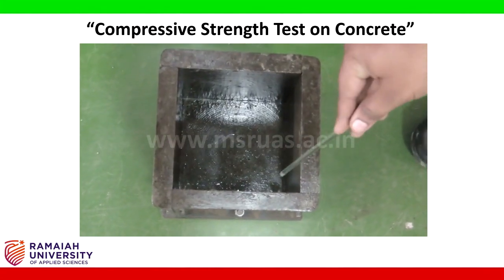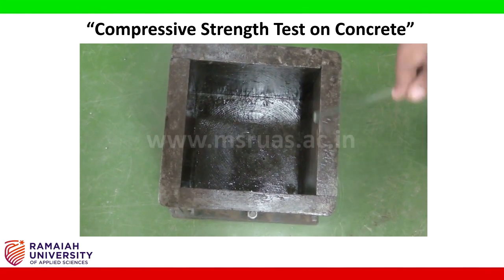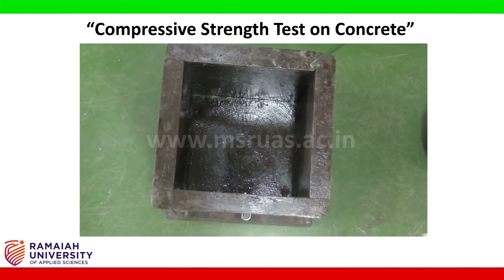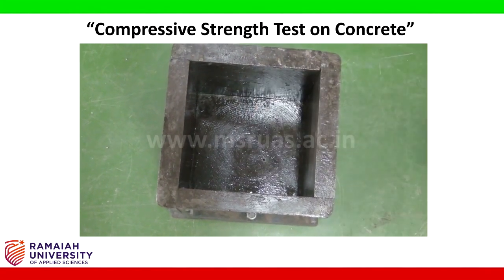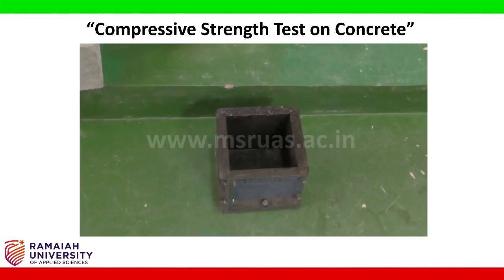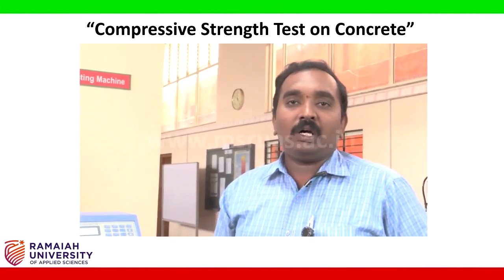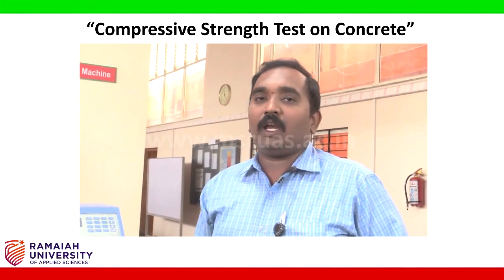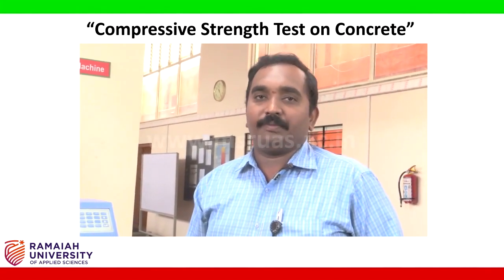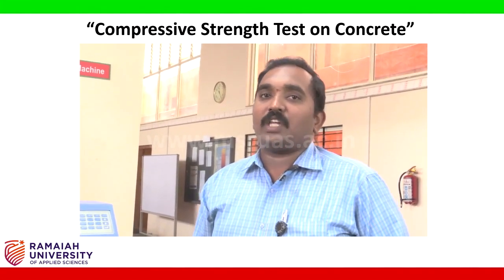This is a concrete cube mold having the dimensions of 150 mm width, 150 mm length and 150 mm depth. Along with that, we require all the materials required for making concrete, that is the fine aggregate, cement, coarse aggregate and the water. So let us go through how this is done.